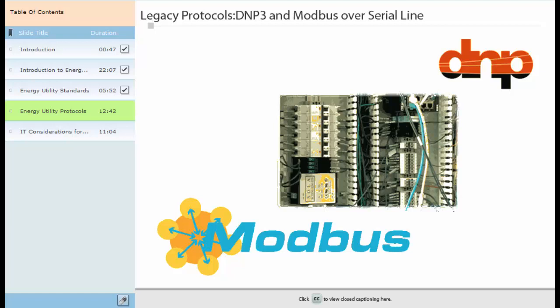The Modbus protocol provides a framework with message structure, synchronization, functional codes, and exception response. The function codes are very specific to the functionality being performed, such as reading coil, reading discrete inputs, writing digital inputs, and so on. Another well-known industrial protocol is Distributed Network Protocol version 3, or DNP3, which is optimized for use in SCADA communication. It is one of the most widely used and supported protocols by SCADA vendors. The goal of DNP3 is to reliably transmit small packets of data with the messages arriving in a strict order.